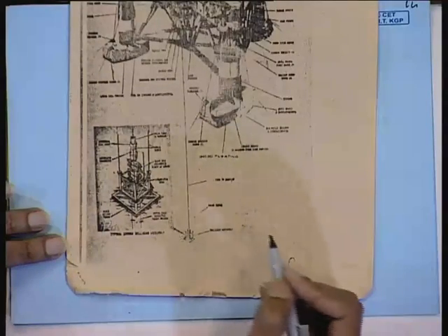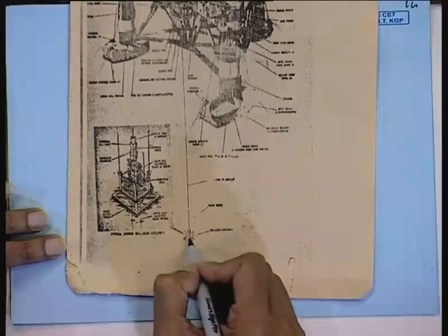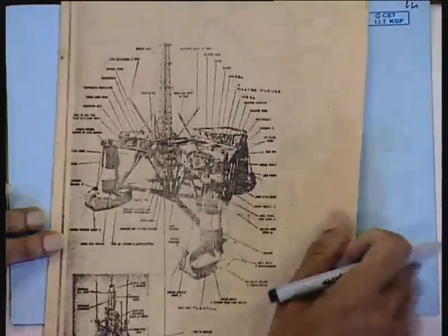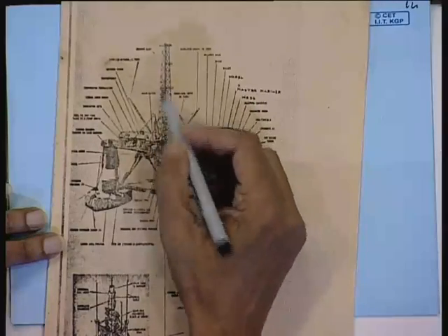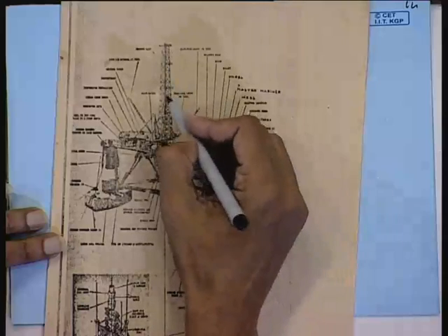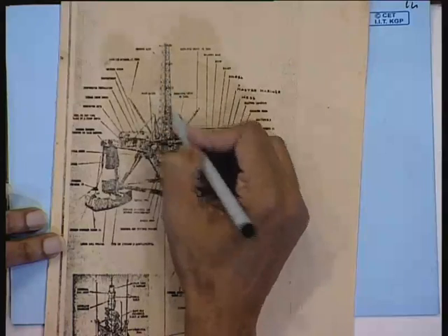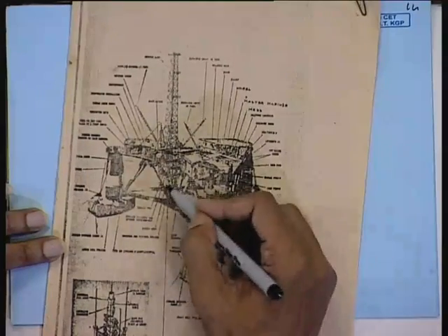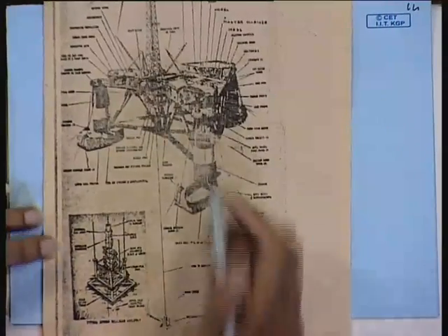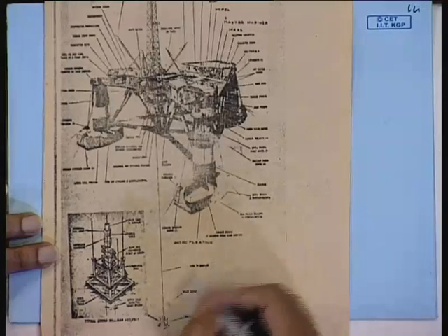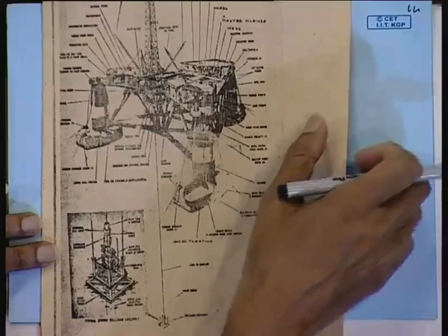This is down below. So, actually your oil is coming through from other wells and it is led to the semi-submersible. So, this is your drilling derrick, and here we have your drill string suspended from the crown block that is going right through this marine riser. This is the typical marine riser. It is connected here to the blowout preventer and top to the deck. So, anyway, this will come back later on.